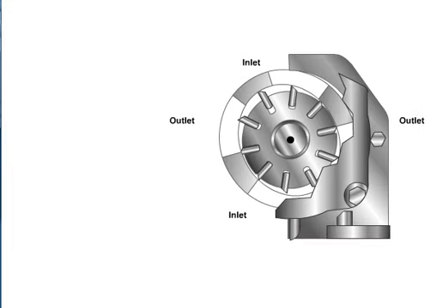It is important before viewing this animation to understand the unbalanced vane pump. If you need to review it, go back and click on Unbalanced Vane Pumps. In the unbalanced vane pump, which has been previously illustrated, one half of the pumping mechanism is at less than atmospheric pressure. The other half is subjected to full system pressure. This results in side-loading the shaft under high pressure conditions.